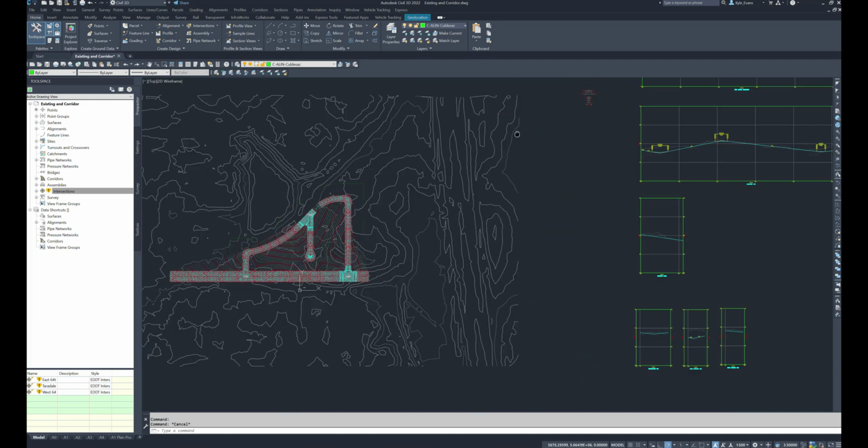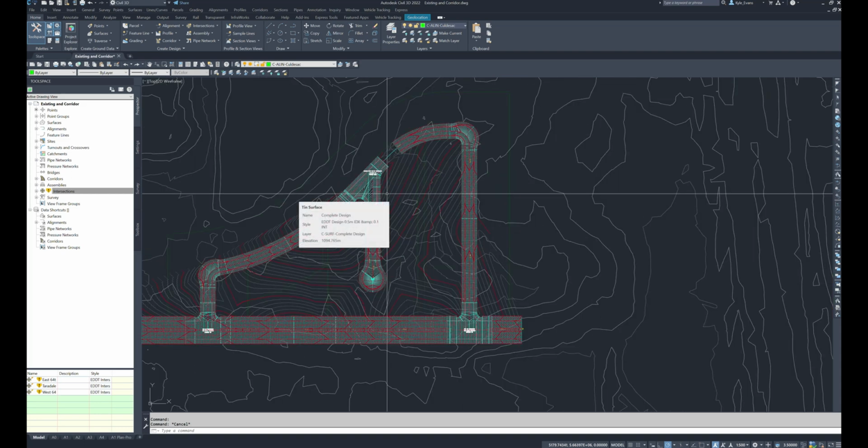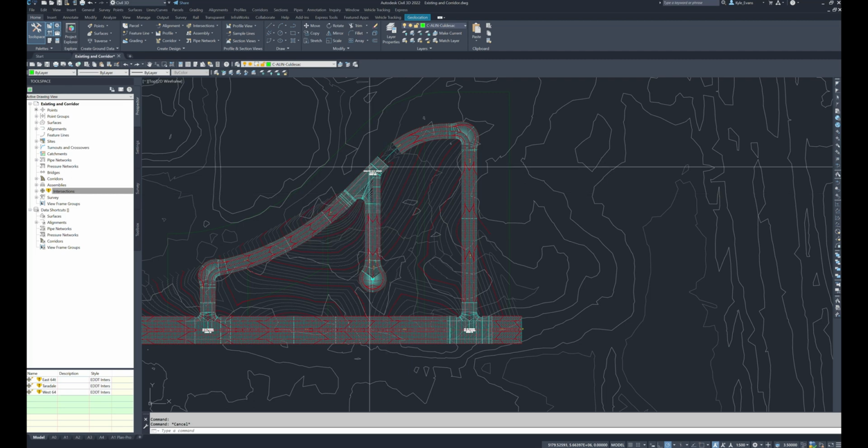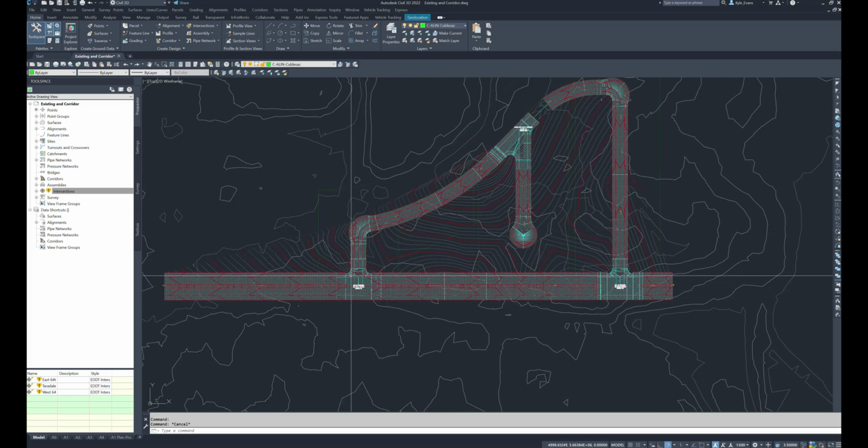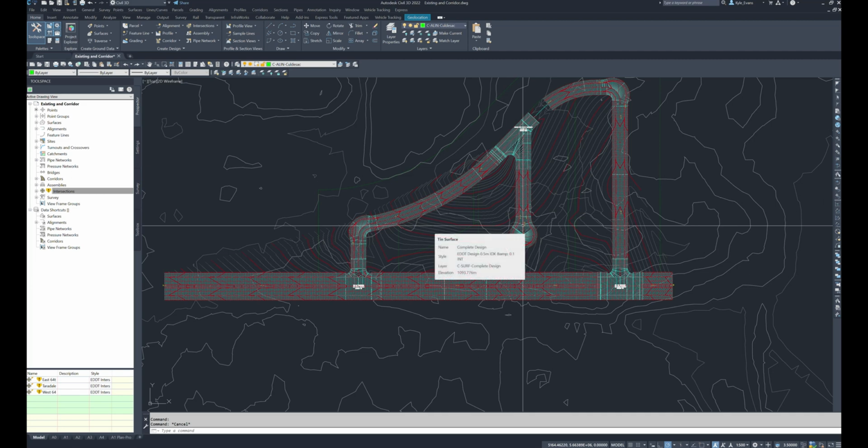And we built a corridor, a residential subdivision corridor out of it, complete with all the tie-ins and the intersections and all the little bits. This video we are going to look at cleaning up some of the corridor areas. We still haven't fixed the intersection up here. We haven't fixed this intersection down here. We haven't added any vertical curves to our knuckles or our cul-de-sacs to make them nice smooth transitions and line up the grades. So we haven't done any of those steps.